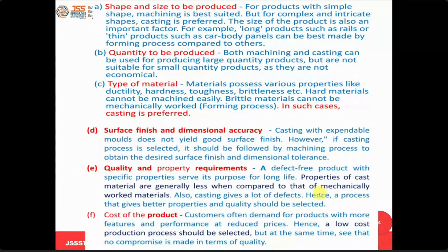Basically, for a complex shape, as we know, we go for the casting process. Casting process is also preferred for large mass production. But if I have a complex shape and I only want to produce one or two products, which method do you prefer? I don't want to manufacture much larger production, I want one, two or three products, that's all. Additive manufacturing. So depending upon the quantity, we need to select the different types of manufacturing process.